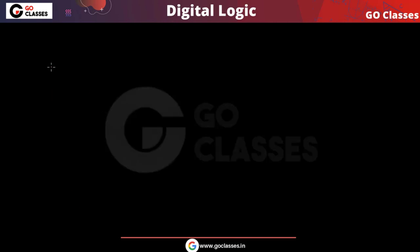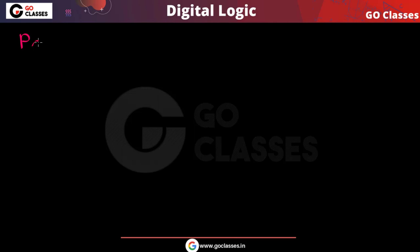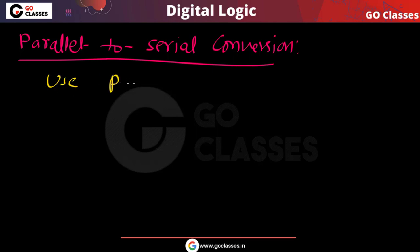First of all, let's see the application where you can use the register for parallel to serial conversion. If you have parallel data, then you can convert that data into serial data. How to do this parallel to serial conversion? Very simple, using a register. Here you can use the parallel input serial output register. This register we have already seen and designed.